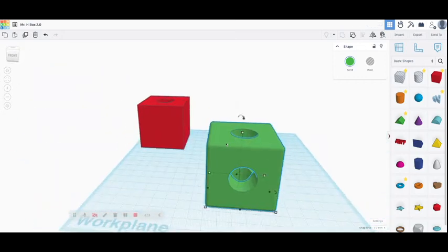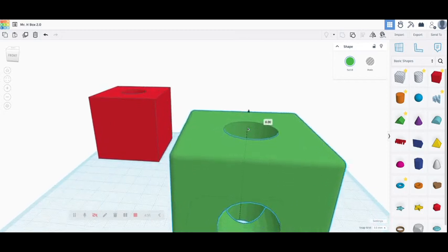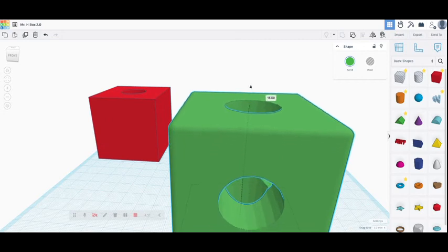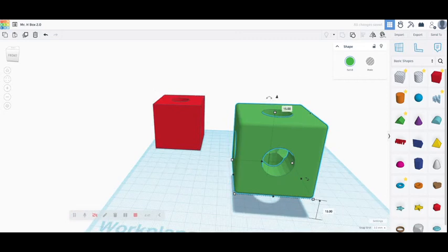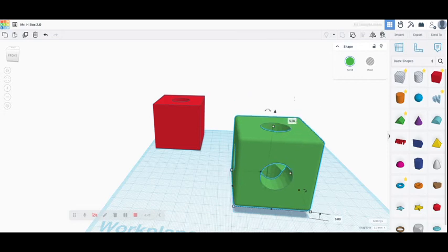The last thing that we're going to learn is how to lift an object off the surface. So what I want you to do is look at this black triangle right here. When we click and drag upward, that allows us to elevate this up into the air. So we're going to elevate that up to 15 millimeters. Now we can type in manual numbers, make it jump to 20. We can click in here and make it drop down to 5. We can make it any height that we want.